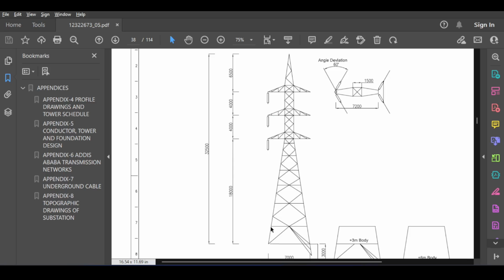No, you are cutting this chord into two pieces because it's practically relevant, meaning that, at least as far as I know, you will not easily find sections that are 18 meters long. So due to practical reasons, you might have to split it into multiple pieces at certain distances. And this is also the case in reality.